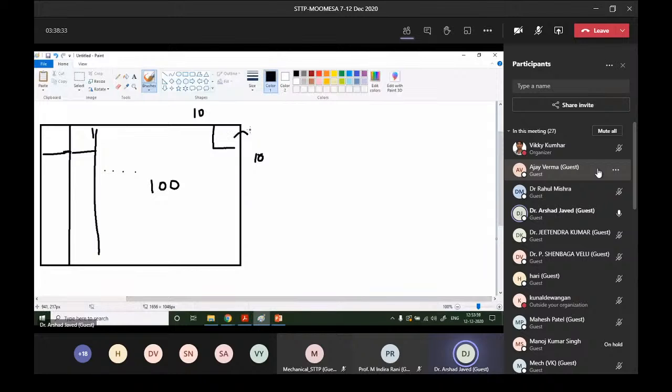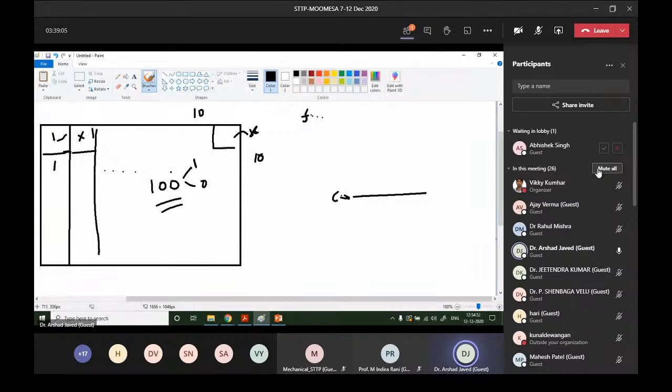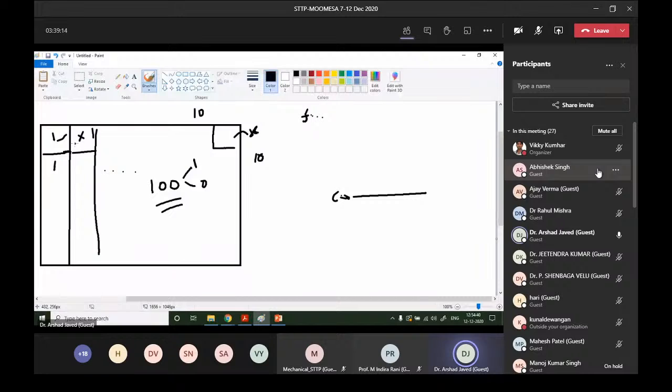And then for each element I defined an x value, and we try to find out the strength or compliance value based on this x. I used 10 for loops, 10 over 10. It means for each combination, here there is material, here no material. For each element, all the combinations of these 100 elements in binary fashion, 1 and 0, were tried. I hope you understand. So it's a crude method in which we try to see how the compliance will vary if I do it one by one.